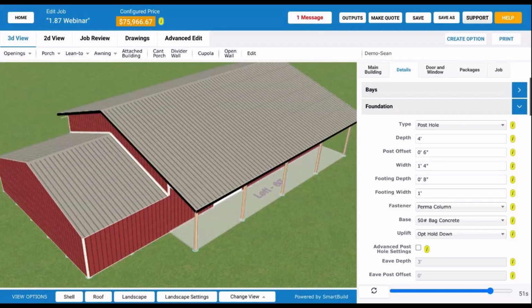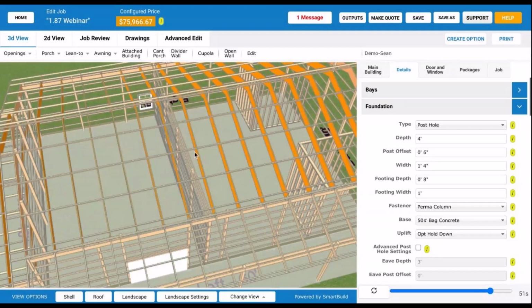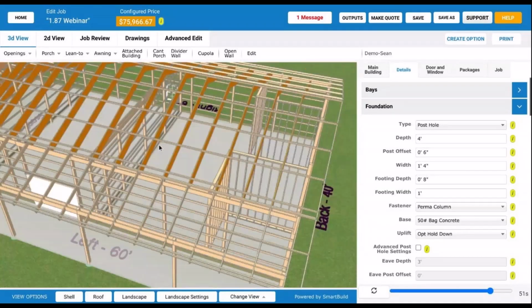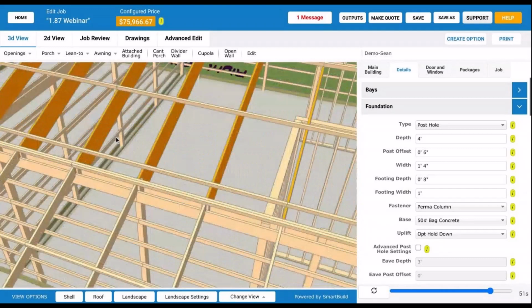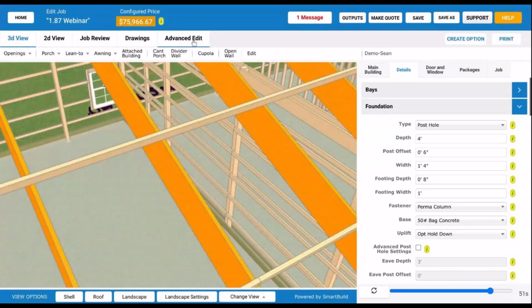Going once, going twice. Timothy just asked, why is there a truss bearer on the interior post frame wall? It's because that's what his exterior post frame settings are. You can go into that single wall post frame and remove it. Just say no truss carrier for that one. But yep, it is going the wrong way.